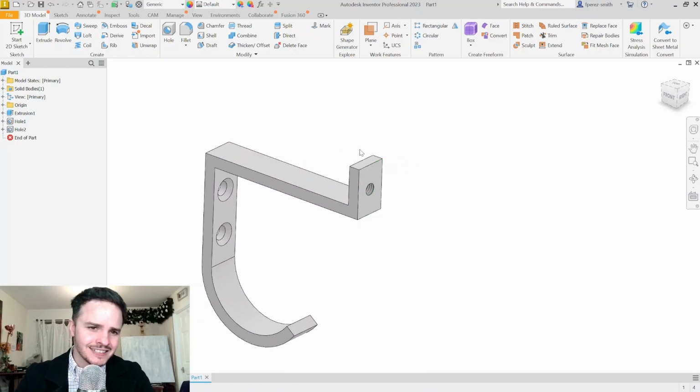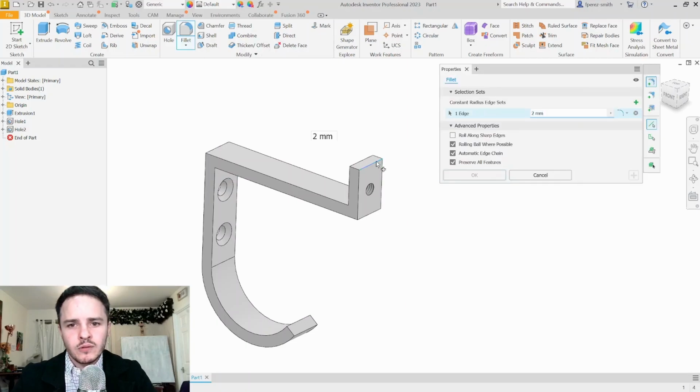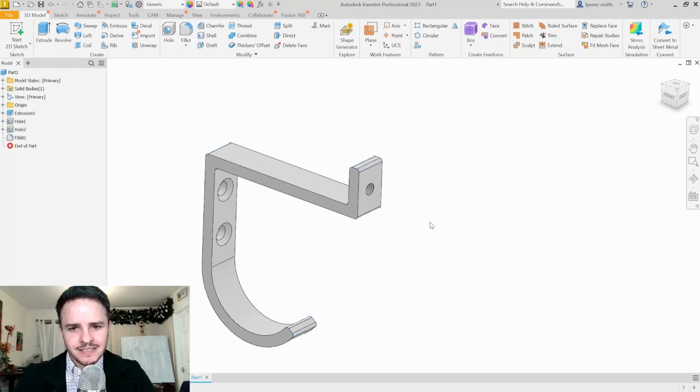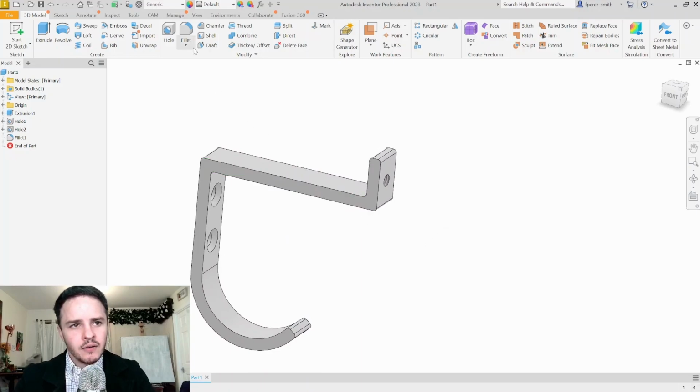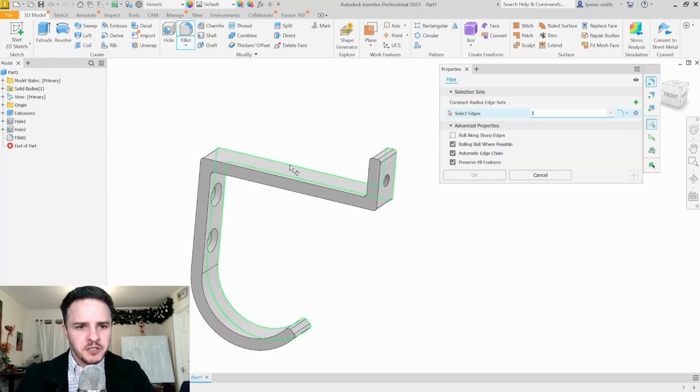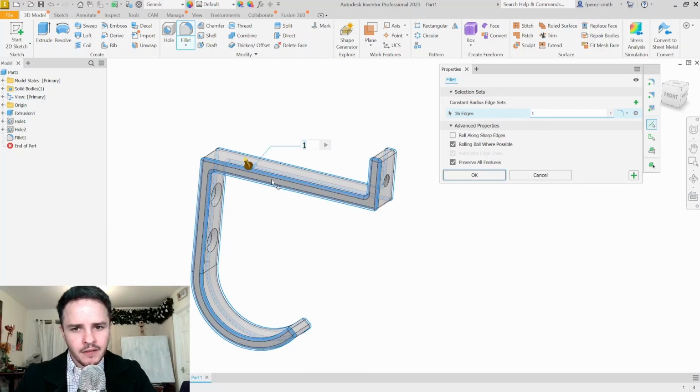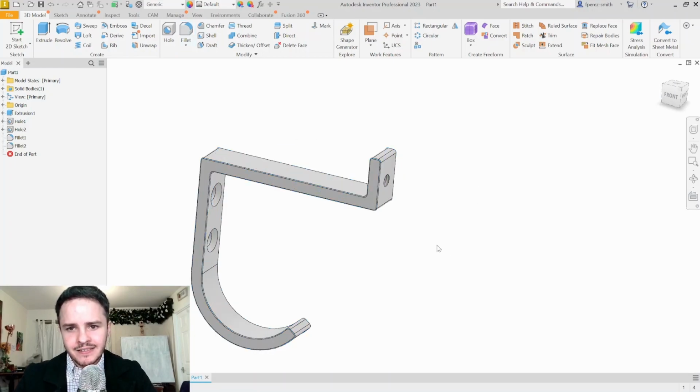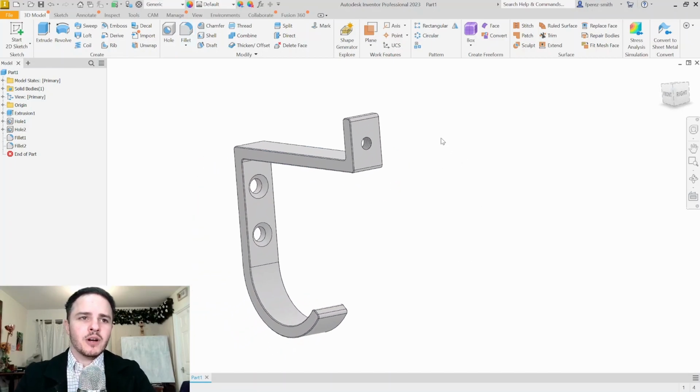Good. Okay, so the last thing to do on this is to get rid of the sharp edges so that no one hurts themselves. So we'll go ahead and add in 2 sets of fillets. The first set, we'll choose these edges here. 3, 4, 5, 6, 7, 8. Cool. And we'll say that is a 1 millimeter fillet. Good stuff. The second set of fillets, we'll say fillet again, and it'll just be for edge breaking, and it'll be around these 2. So we'll say 0.25 millimeters. Good stuff. Cool. So we have our geometry.